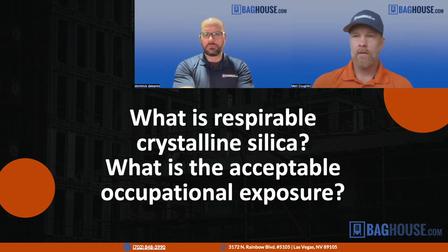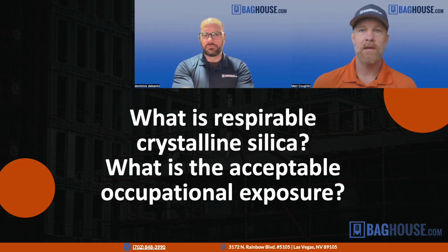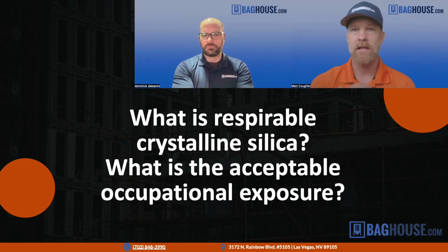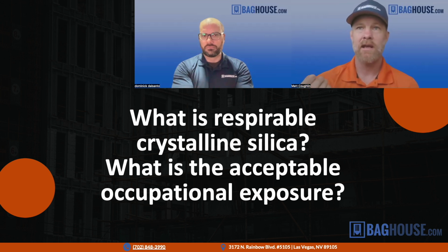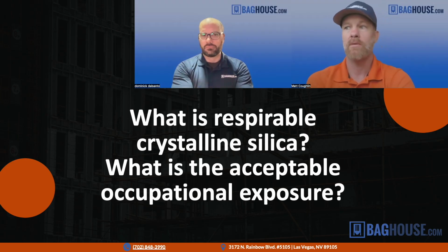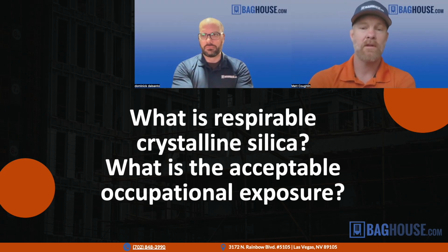Yeah, respirable crystalline silica is basically silica dust, but it's so fine that it can be breathed in, or it's respirable, and it's of a certain size. The standard is so small that you typically cannot see it as airborne dust, but you can breathe it in, and it can cause all kinds of problems. Like, there's lung conditions that are specifically attributable to respirable silica dust.